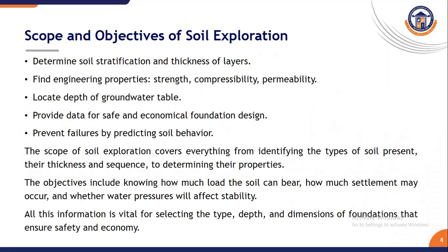They also provide data for safe and economical foundation design and prevent failure by predicting soil behavior. The main objectives include knowing how much load the soil can bear, how much settlement may occur, and whether water pressure will affect stability.